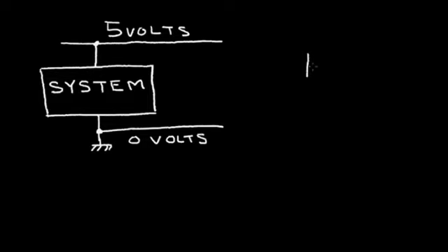I have an LED that is rated at 16 milliamps at 1.8 volts across the LED. And the LED has a maximum current rating of 25 milliamps.